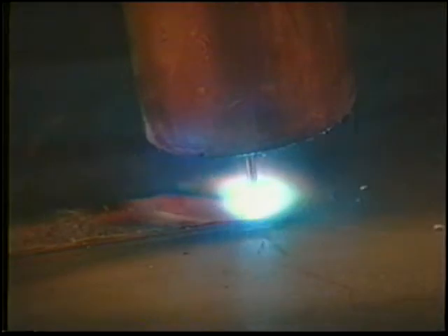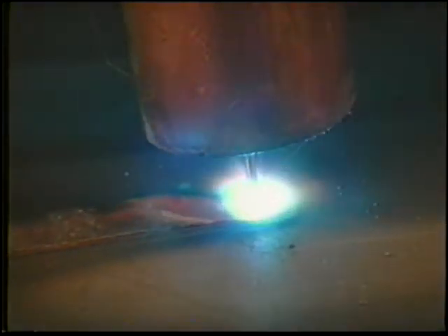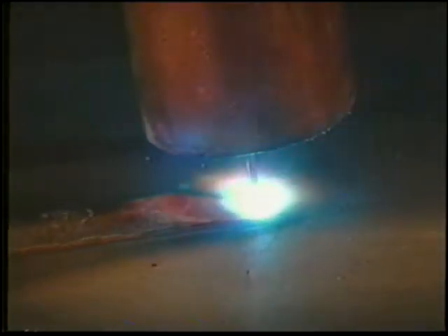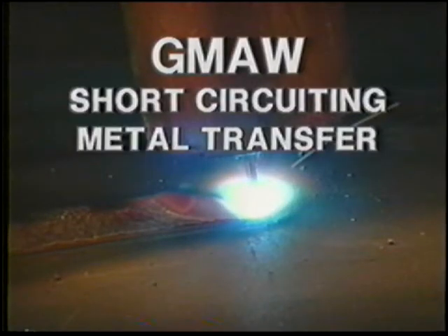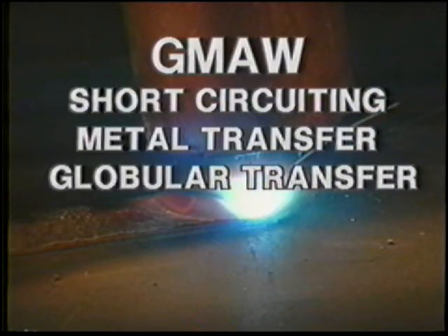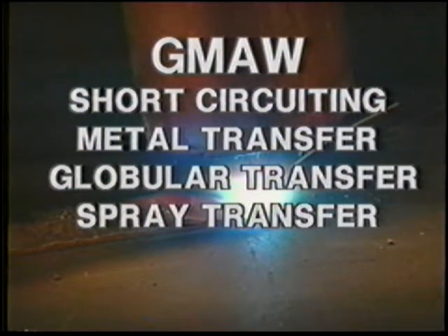The characteristics of GMAW are best described by the four basic modes of metal transfer which occur with the process. These are short-circuiting metal transfer, globular transfer, spray transfer, and pulsed spray transfer. The type of welding to be done determines which of the transfer methods to utilize.